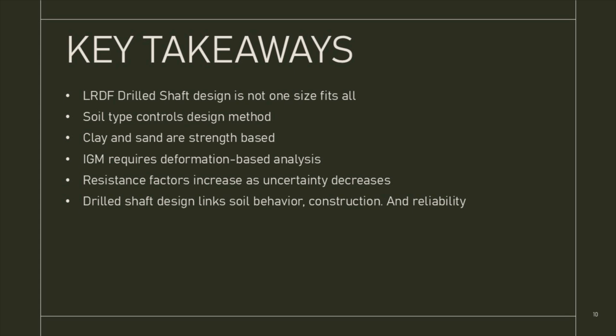By explicitly evaluating load transfer with movement, the IGM method provides greater confidence in predicted capacity. As uncertainty in behavior decreases, resistance factors increase. Across these 5 examples, LRFD consistently ties reliability to our confidence in the prediction method.